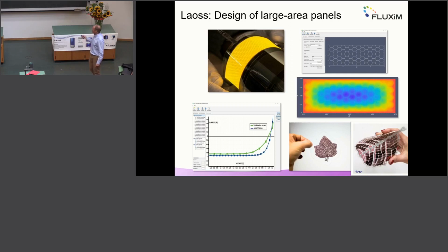And usually what we do here to compare is we input the properties of a very small solar cell. So it would be this blue curve with a nice fill factor and a nice photocurrent. But if the solar cell is getting large and the transparent electrode is not ideally conducting, then we lose in fill factor. And that's the gap we want to minimize here, from the small cell JV to the big cell JV. There is a gap in fill factor and efficiency.